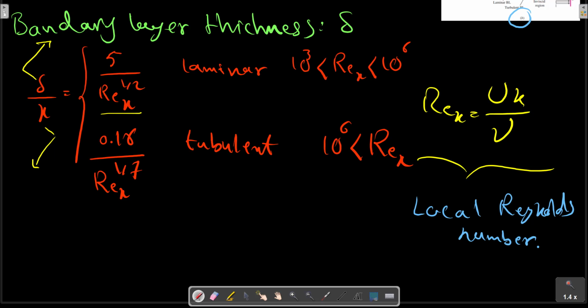For a blunt body flow, however, even at a very high Reynolds number, there is a discrepancy in the viscous-inviscid patching concept. Consider this picture, which shows a sketch of the flow past a two or three-dimensional blunt body.